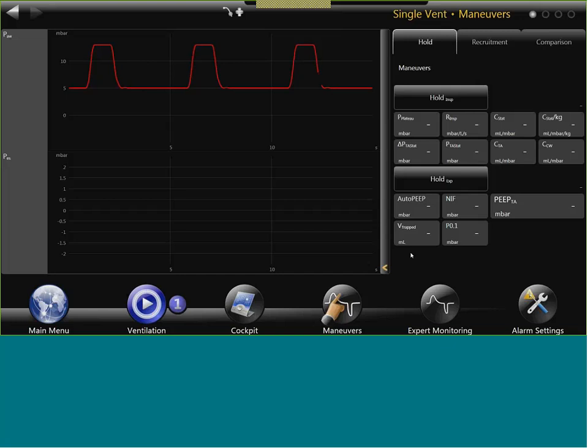Next one, Sahi is asking, is there a recommendation for the set of filters PM kit to be replaced on monthly basis? In case of continuous working of the machine, how do we replace the filters then? Can those be replaced once the machine is free? Oh, they can be replaced during operation. So there's no reason to replace the filter only when the machine is not running.